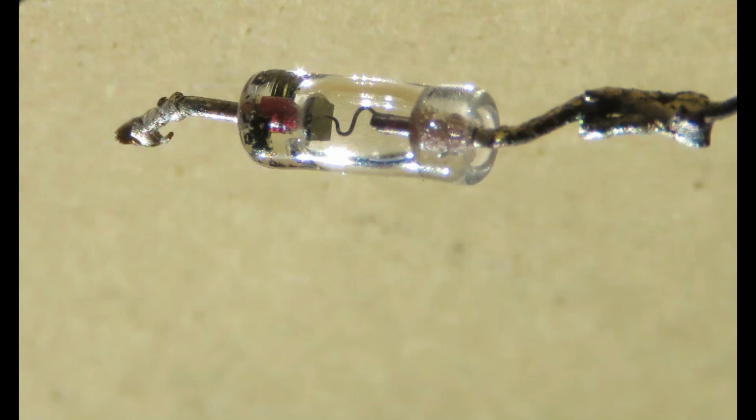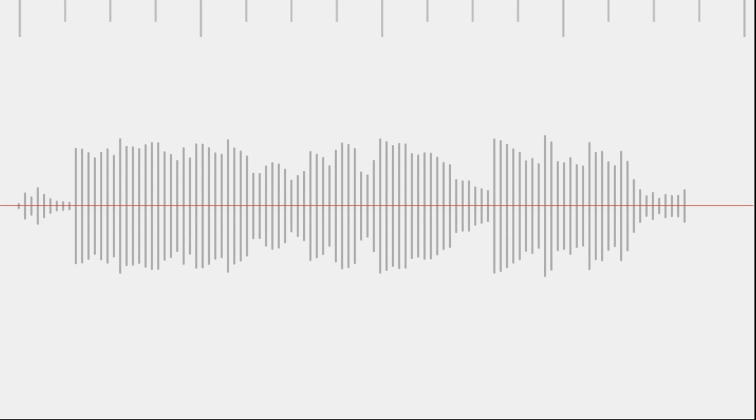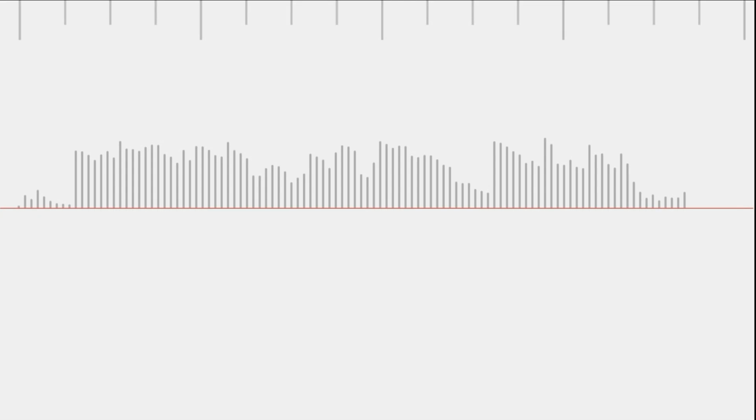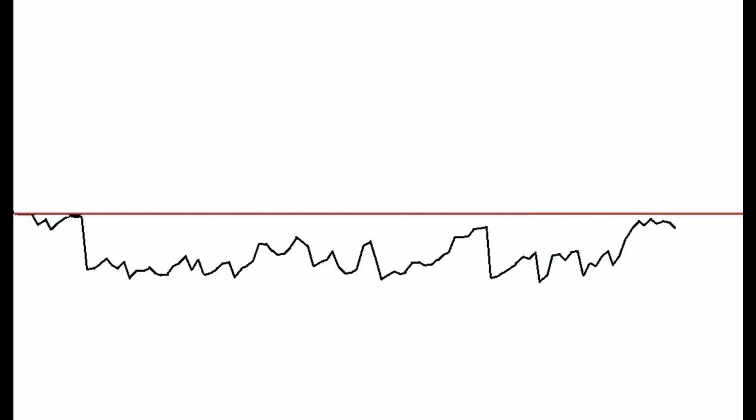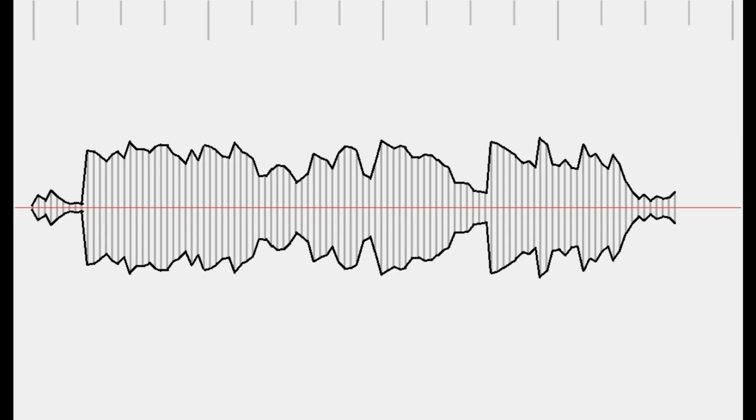Our diode in the circuit we are developing is going to be a radio detector, or RF demodulator. RF stands for radio frequency. We rectify the radio signal to get the audio information from the modulated RF wave, because all we need is the envelope, which is the tops of each of the tan vertical lines of the envelope, shown in black. Incidentally, you can use the negative envelope, as some circuit designers prefer to do. We'll get more into modulating and demodulating in the next video in this series as we add the diode to the circuit.